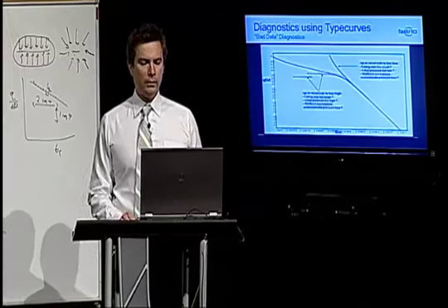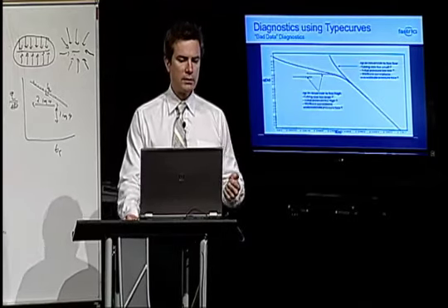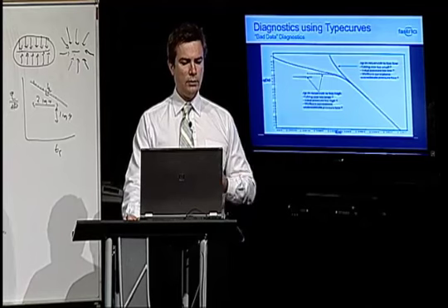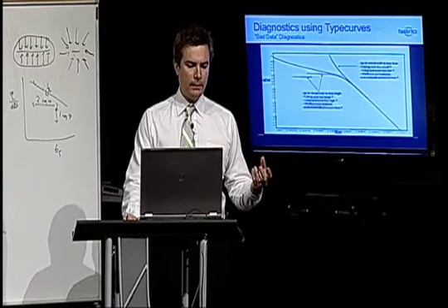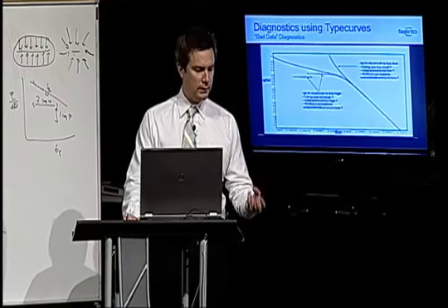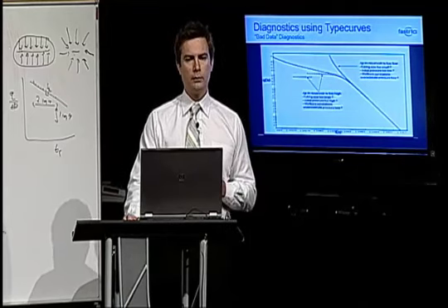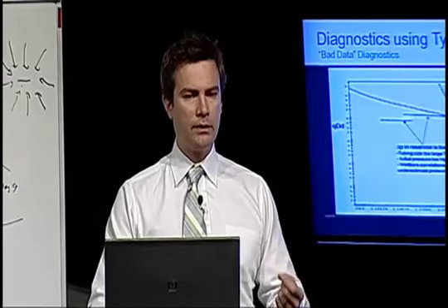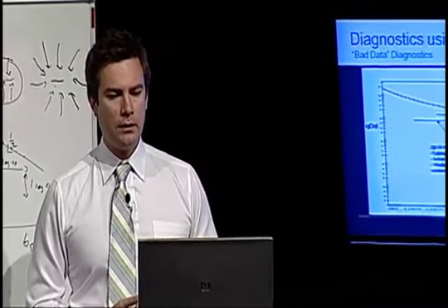One example where wellbore correlations can overestimate pressure loss is when you have assumed that liquid condensates or liquid water rates were in the liquid form while they were flowing in the wellbore. Many times these fluids come out and are only fluids once they've been separated in the gas separator. In the wellbore, because we've got high temperatures, they may all be in vapor form.